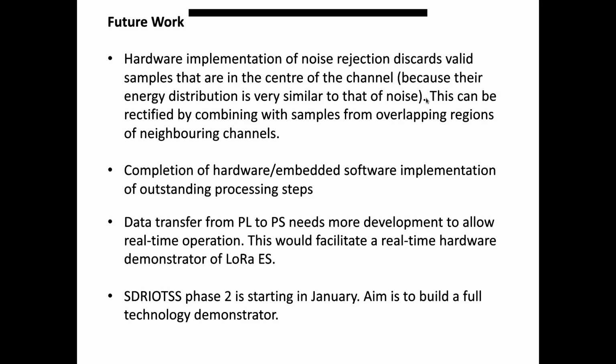So moving on to future work in this area, that's what we've accomplished so far, but there's still quite a lot to do on this project. I talked a little bit about this DC leakage through the channelizer causing this kind of steepening in the distribution of energy of the noise signal. This means that at the center of the LoRa chirp, it looks quite a lot like a noise signal to the noise discriminator, and so a lot of those samples get thrown away.